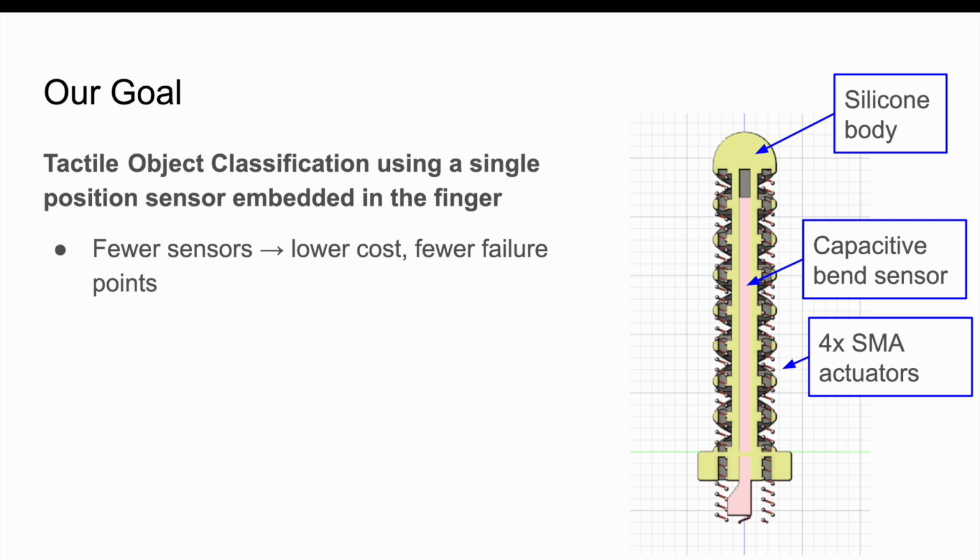Our system used a capacitive band sensor for position feedback, an SMA actuator for the deformation and the motion, and a silicone body for compliance. We aim to extract the useful tactile data with minimal hardware.